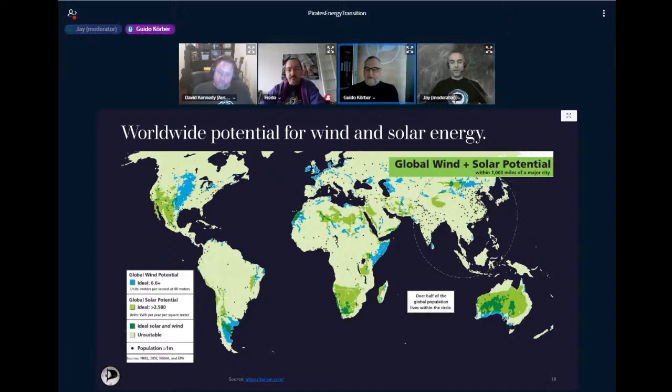Yeah, that works to some degree, but of course it's also connected with a lot of cost. And you always have to keep in mind how much it costs to transport the energy versus how much cheaper it is to produce it at a different place. And that's a point where I'm very, very skeptical about transporting any energy over really long distances, since you have losses, even if high voltage DC is quite efficient, but that also makes the system more expensive. And it also takes a lot of maintenance.